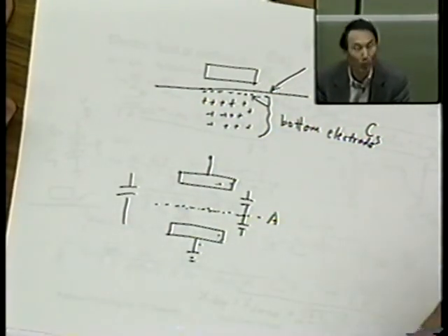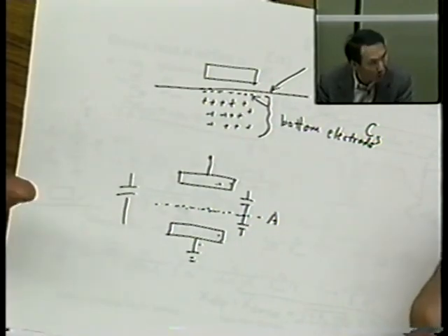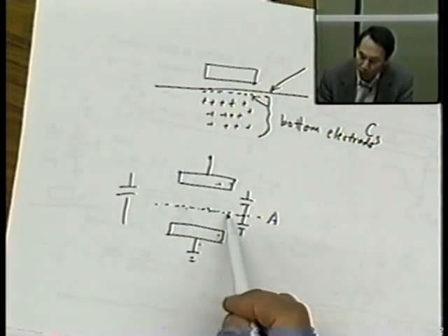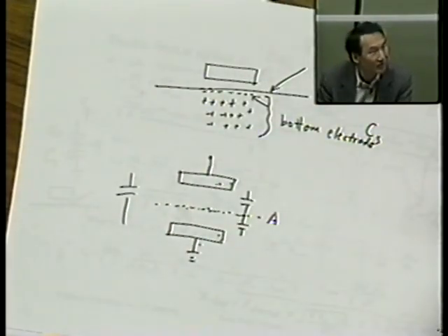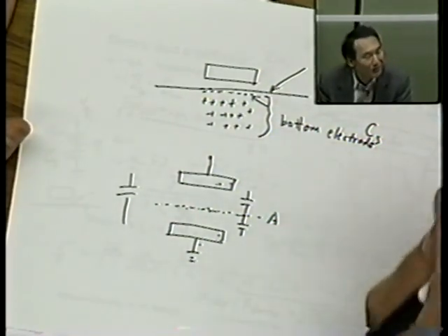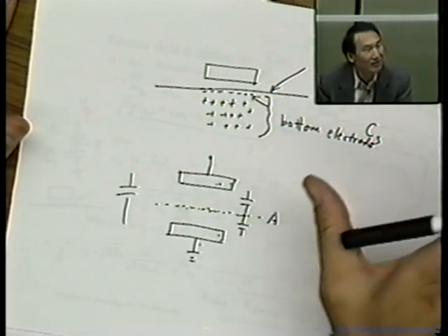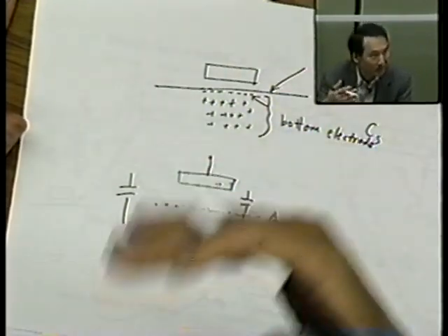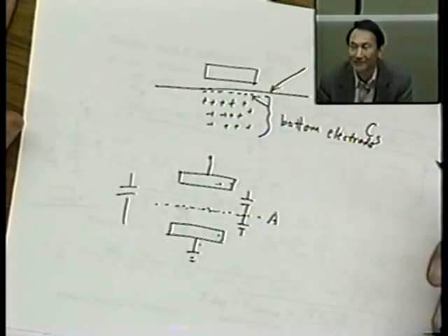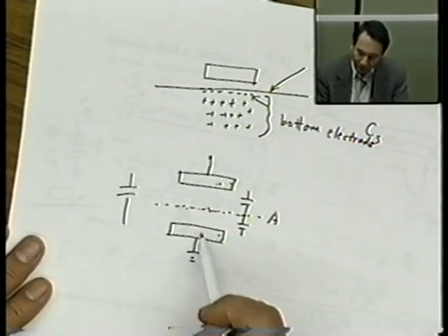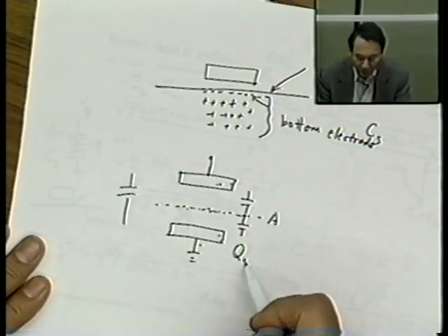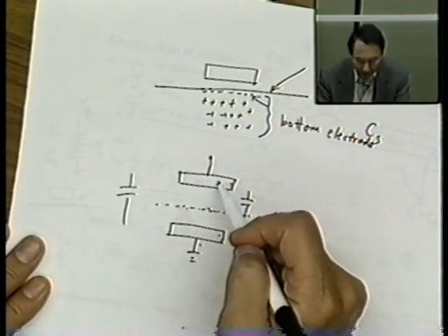But it's just as real and useful an electrode as thinking there was an electrode at the interface between oxide and nitride. So we can think that there are two capacitors in series. That's the electrode we're thinking about. There's no charge at that surface, and the charge of the inversion layer belongs to the bottom electrode.